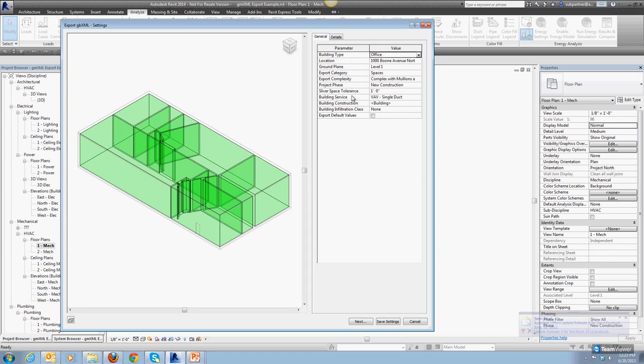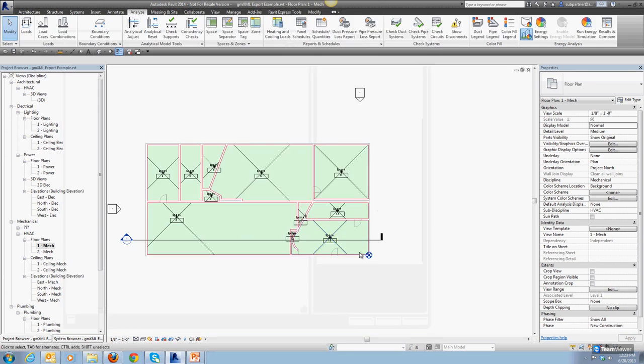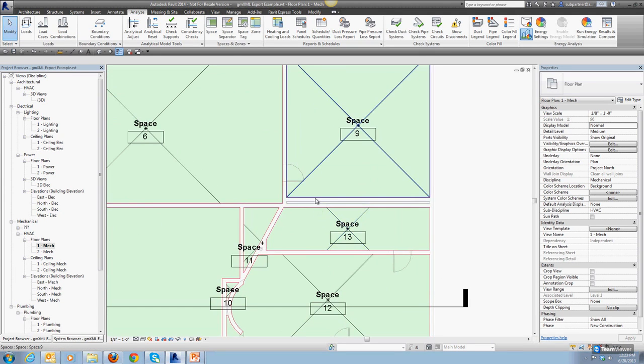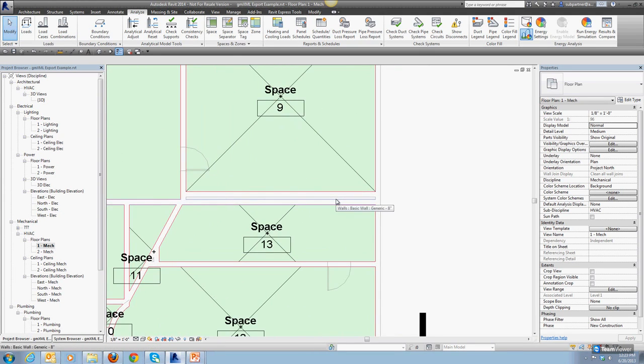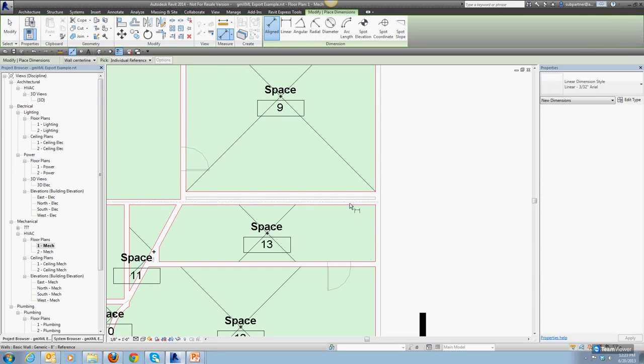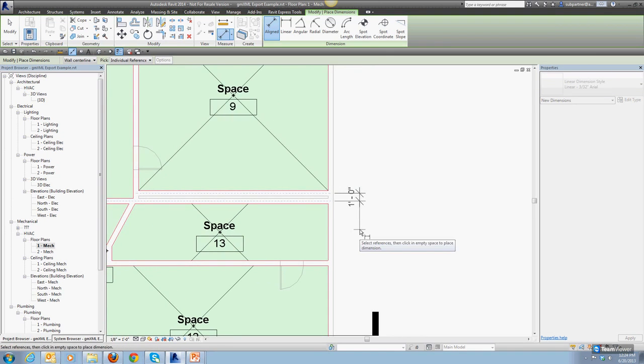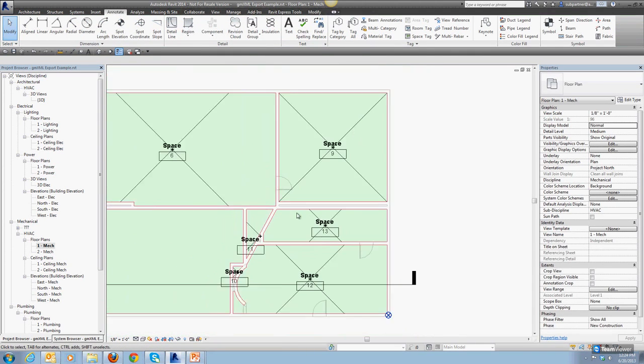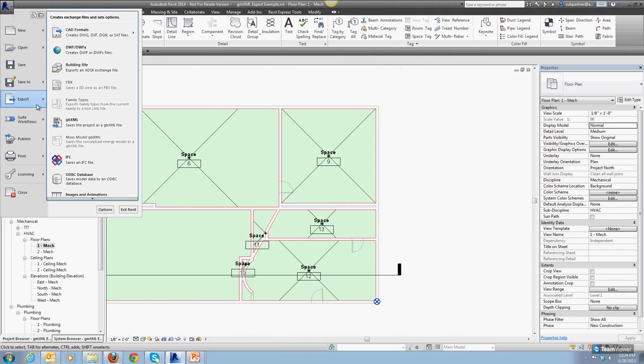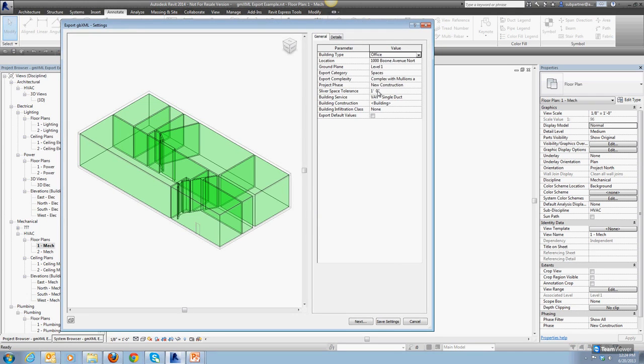Now let's take another look at this sliver space tolerance setting that you have. The sliver space tolerance is set at 1 feet. I'll just save settings and do a dimension for the distance between these walls. If I go to Annotate and do a dimension here, the dimension between these wall items is 1 feet. So my sliver space tolerance also has a value of 1 feet at this point.